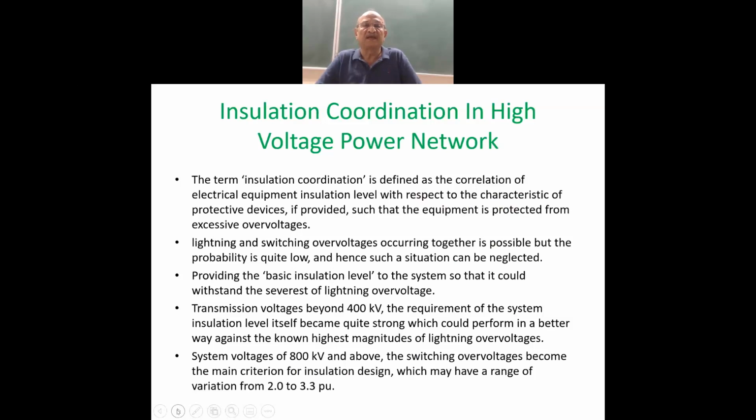So zinc oxide has a characteristic to provide a low impedance path to the short duration pulse, but a very high impedance path for power frequency voltages or current.